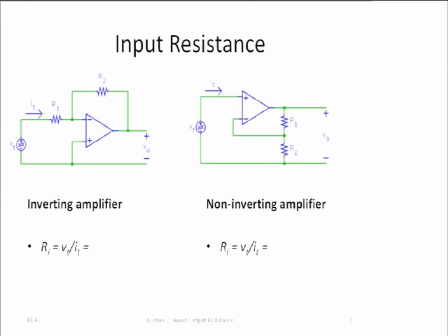Well, what is this test current? Whenever I want to measure the input resistance, what I really do physically in the lab is connect the source, maybe the lab power source, to the input of my circuit. I call that VT, the test source, okay? And then I measure the current, right? And the ratio, that's the resistance, at least for that voltage. So in this case, what is IP? Yeah, exactly. That one's 0, and consequently, this one is on the other limit. It's very, very large.